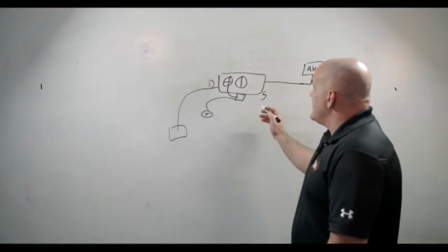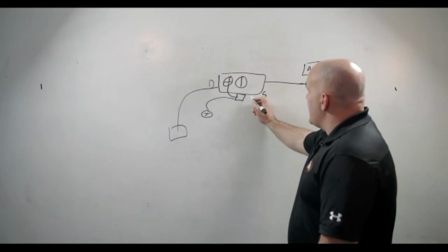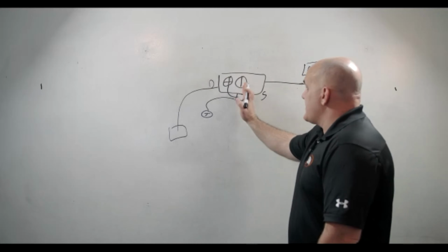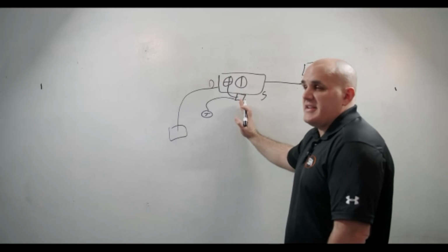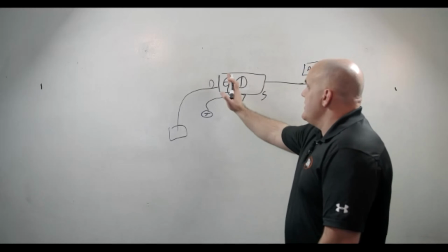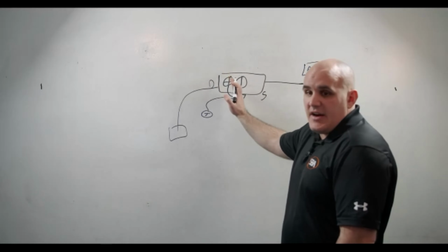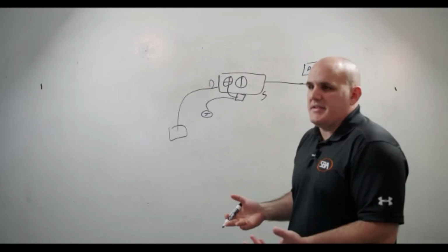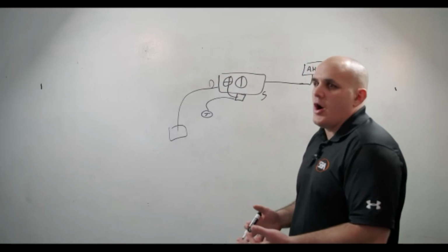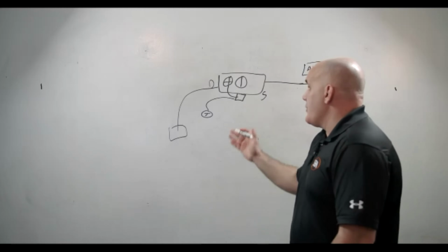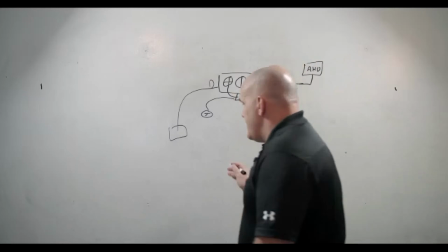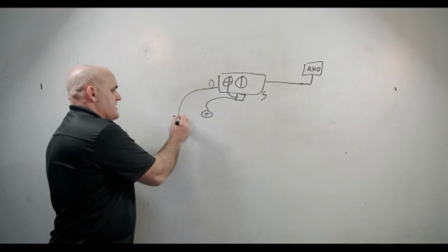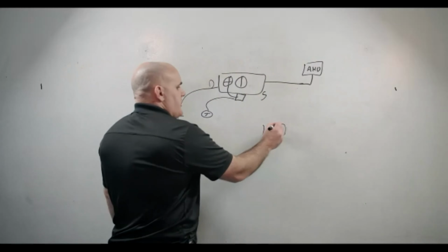And if we get that air is coming in and temperature is right, and we've checked our actuator and validated that it's stroking correctly, and we validated that we have the correct airflow, we've checked the balancing settings if we have them written down, or our equipment schedule, and we validated that that's accurate, then the only other thing it could be is either on the supply or on the exhaust side.